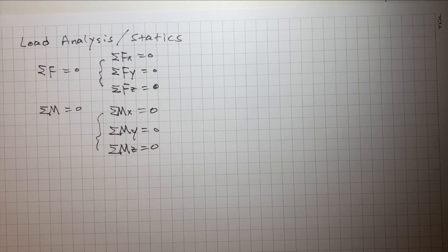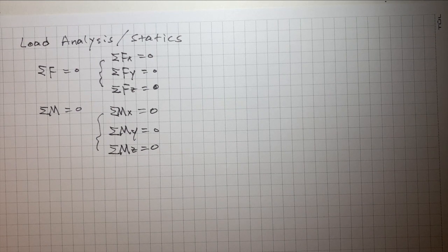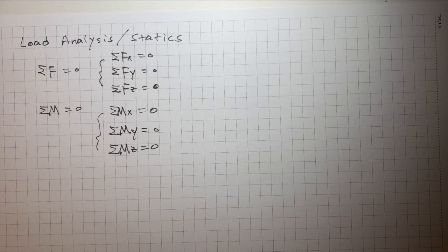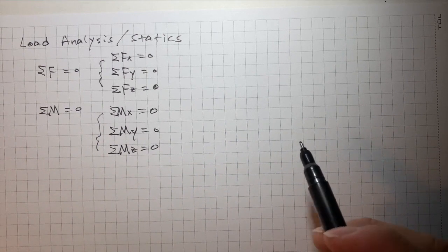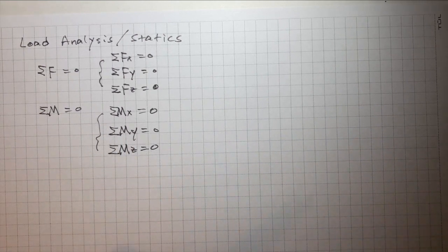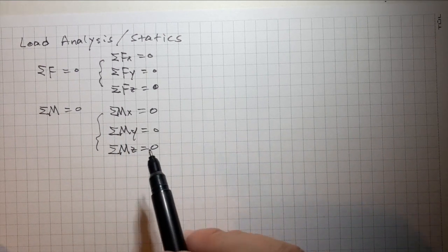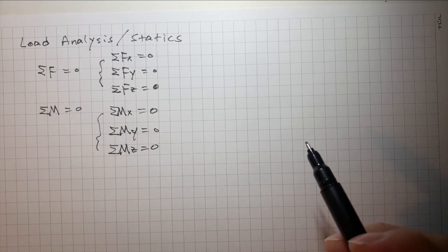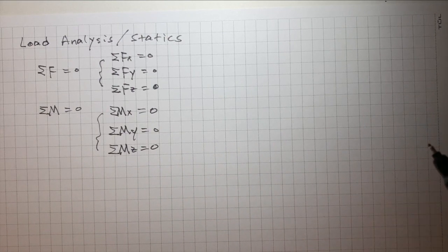So basically, for any statics problem, you can write 6 equations, and you can solve 6 unknowns. So this is very important. You need to know how to write the force balance equation and the moment balance equation.